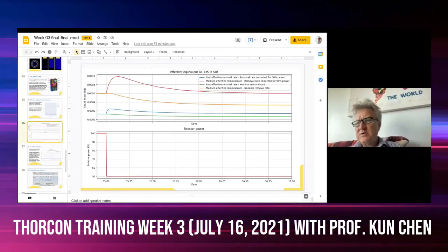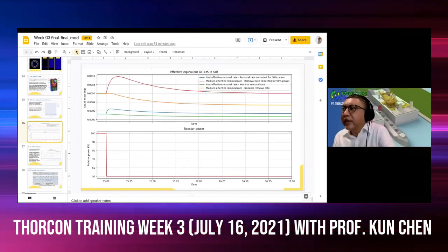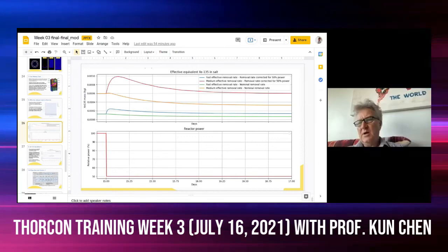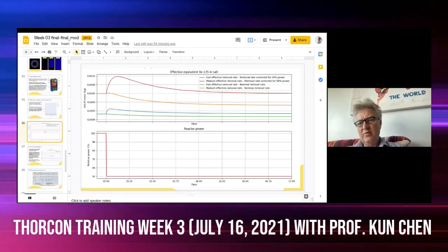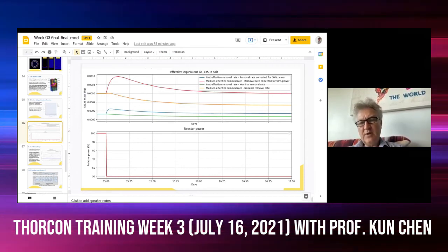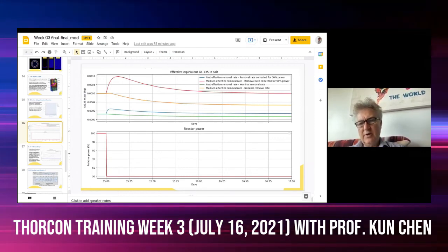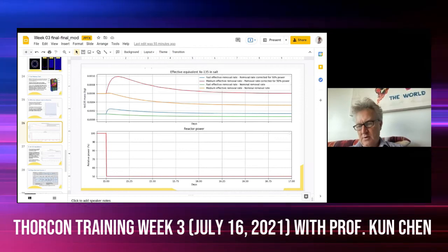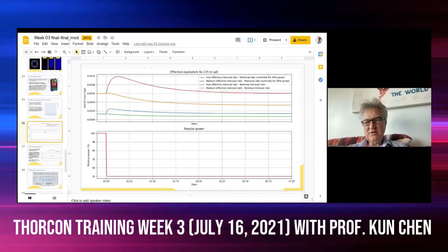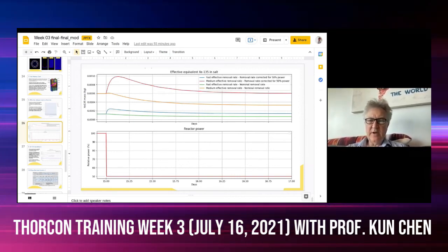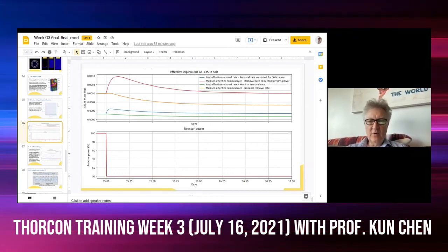What was the next question? What does it do to the conversion ratio? Yeah, for the 4 years burning time. I think the more important question would be, if we have no thorium in there, then we have more uranium in there. And we need to keep the uranium fraction, because uranium is our redox balance. So it's our chemical buffer, and we want to keep the ratio of UF3 to UF4 at about 1 to 60.